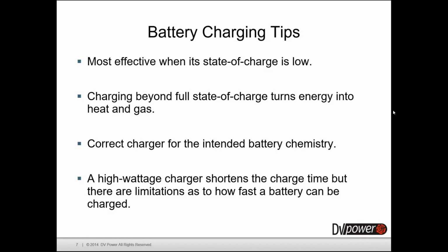So when you are charging the battery, you will see that from, let's say, 30% up to 75%, you charge quite fast. And then from 75 up to 100%, it really takes time. And that is because the battery is converting electrical energy into chemical energy more slowly when above this 70% state of charge.